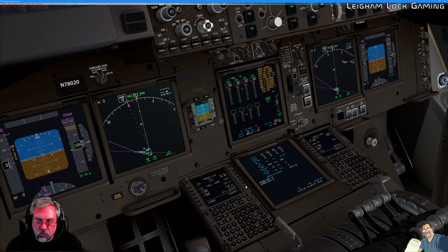We can go on to thrust limit. We're only half loaded. The weather is pretty decent. It's actually surprisingly warm for the time of year. We are in winter. We're going to do a derated takeoff, number 2, so 90.8% thrust. And then from here, we want to go to our takeoff specs. Today's takeoff is going to be pretty much a standard takeoff using flaps 10.